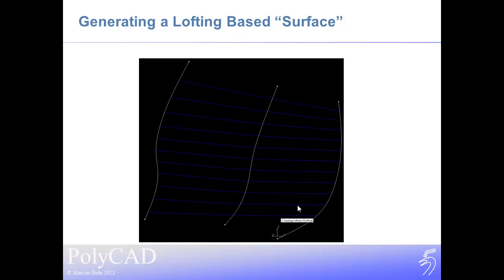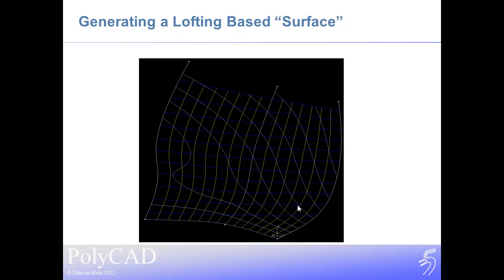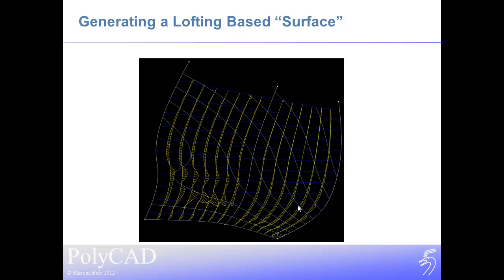And then we repeat that process. So we repeat that process for a set of buttocks, for example, and for a set of waterlines. And because we're only dealing with cubic splines, this process is incredibly quick. But it does start to pick up some interesting facts about our curves. We can generate the curvature straight away from our curves, far easier than trying to evaluate the surface.